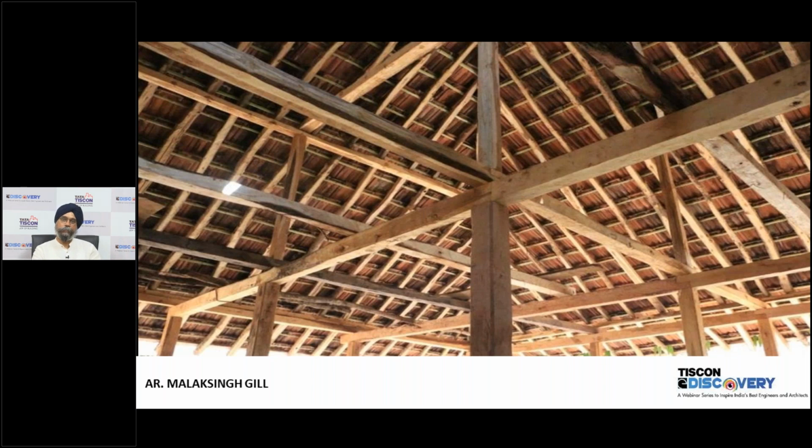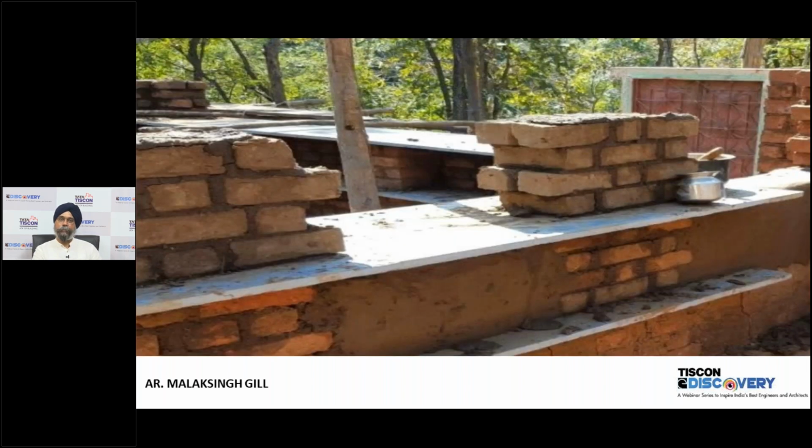This is how the roof works out. All local timber and treated with the local preservatives. They make a kind of concoction of the mahua flowers, which is abundant in a season, and then they basically paint it with that. Then that's an excellent preservative.